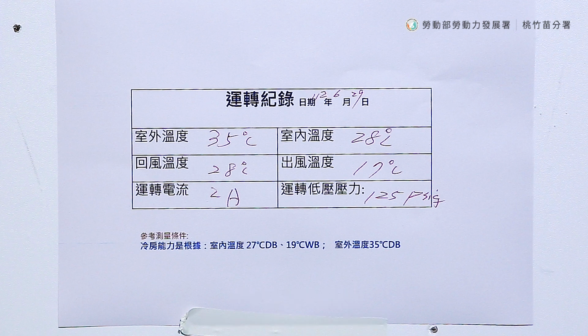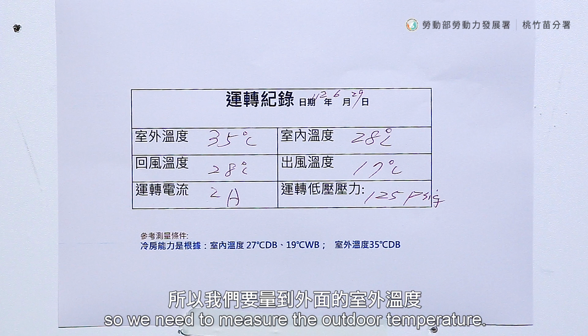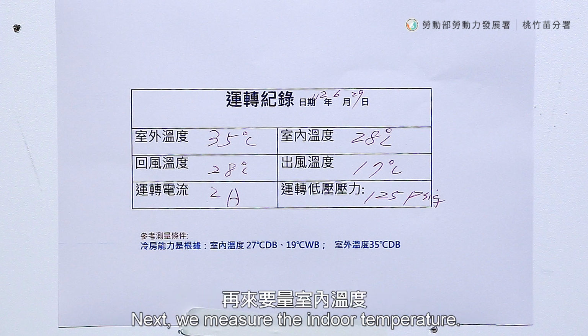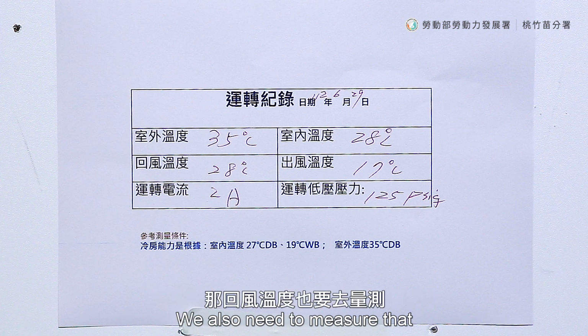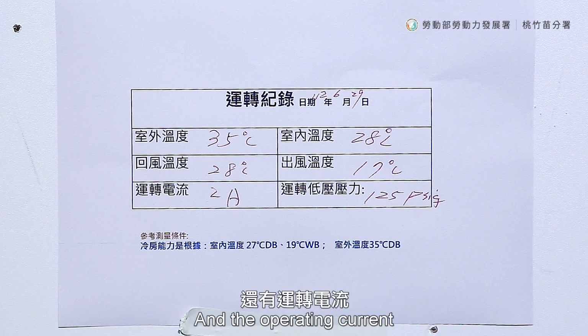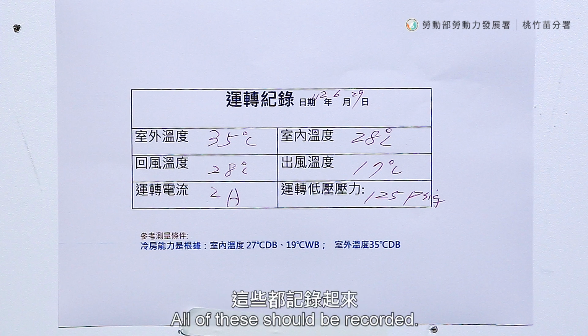Outdoor temperature. It has to do with the external environment, so we need to measure the outdoor temperature. Next, we measure the indoor temperature. Indoor temperature is close to the return air temperature. We also need to measure that, and the temperature of the supply vent, and the operating current, as well as the low side pressure. All of these should be recorded.